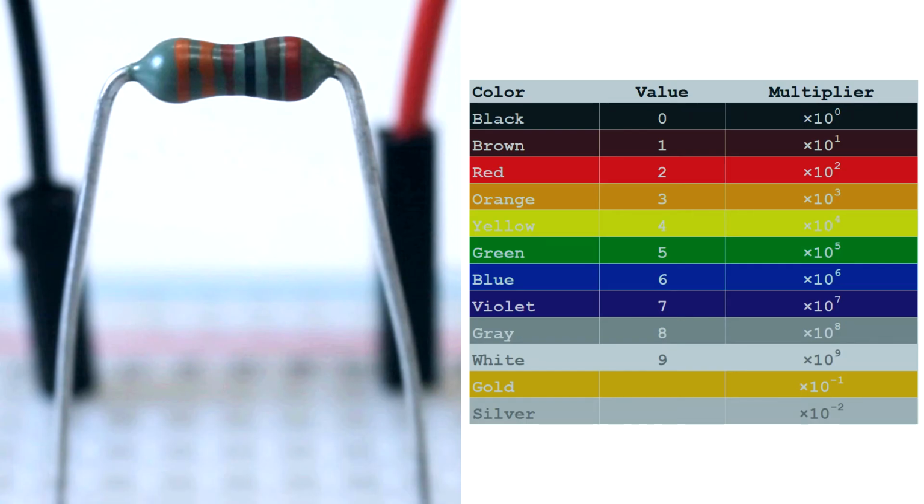Next, a 6-band resistor. The bands are from left to right, orange, orange, brown and black, which equals a 331 ohm resistor. Great! Now we know how to calculate the resistances, but what are the other bands for?